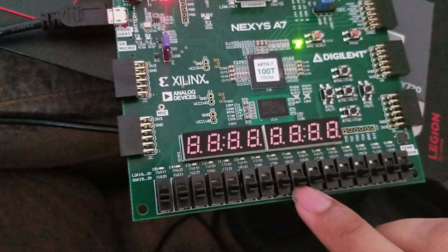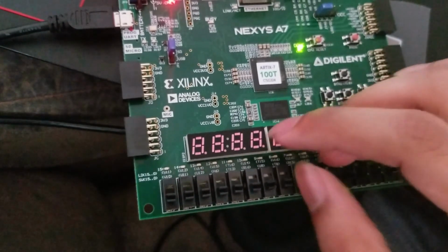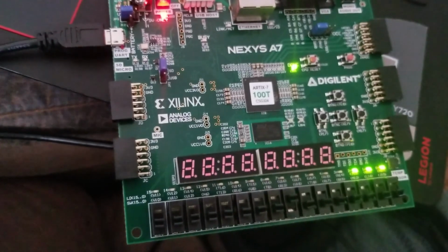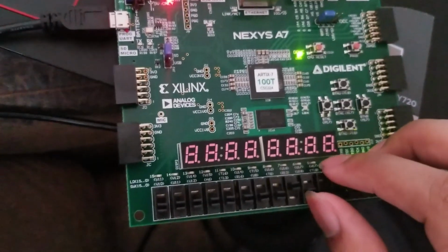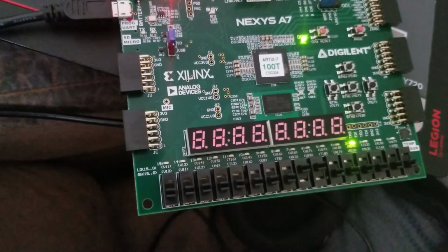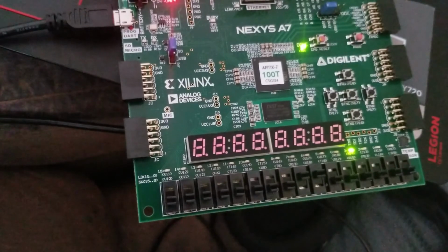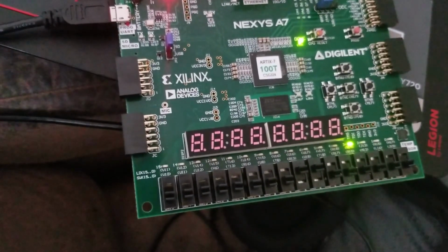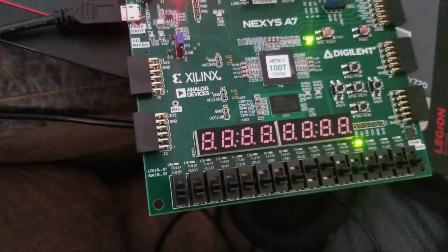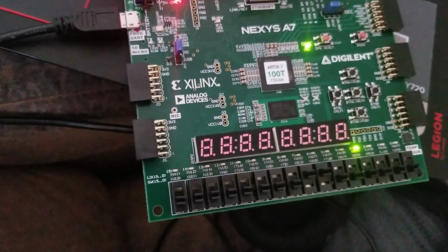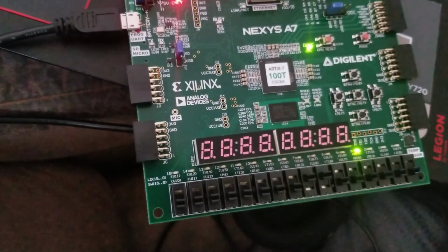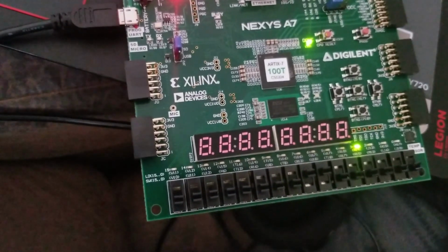So let's go into subtraction mode by putting mode 0 up to 1. Right now you'll see all 1, 1, 1 because of the 2's complement of B, but that's just flipping bits. To do the full 2's complement, you have to turn C in up to 1. Now we see that our sum is equal to 0 and our C out is equal to 1. In a future version of this code, we would probably have thrown out C out in subtraction mode, because the C out really has no actual representation of anything in subtraction.